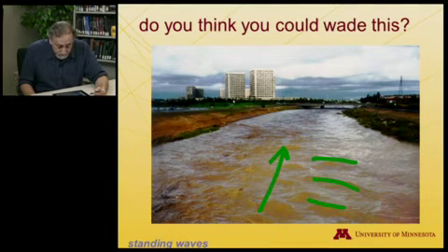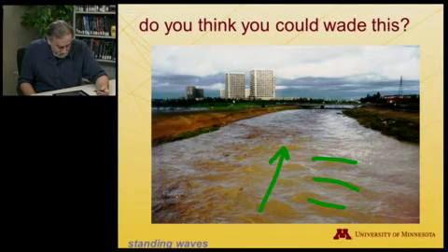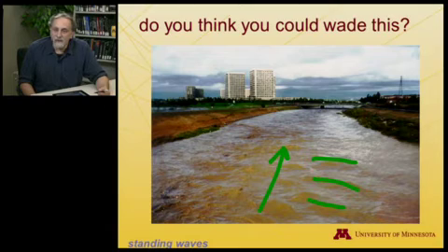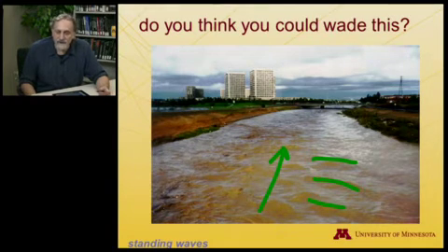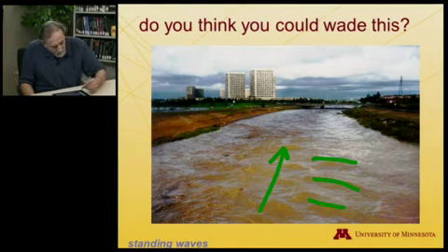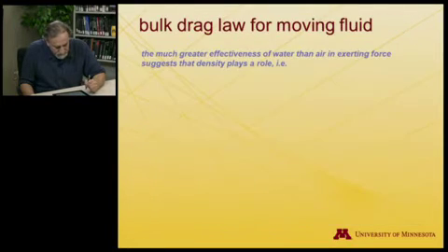So, in fact, there's a rule of thumb that we were taught in the USGS when I worked for them, that if the product of the speed and the depth in MKS units was more than 1, you couldn't wade in it. And that's a pretty good rule of thumb to live by. So the speeds at which you can't stand up in water, in which the water is exerting enough force on you to knock you down, are much, much lower, an order of magnitude lower in water than they are in air. And hopefully that suggests to you that there's another effect than speed, and that is, not too surprisingly, the density. So that's what we're going to look at now.